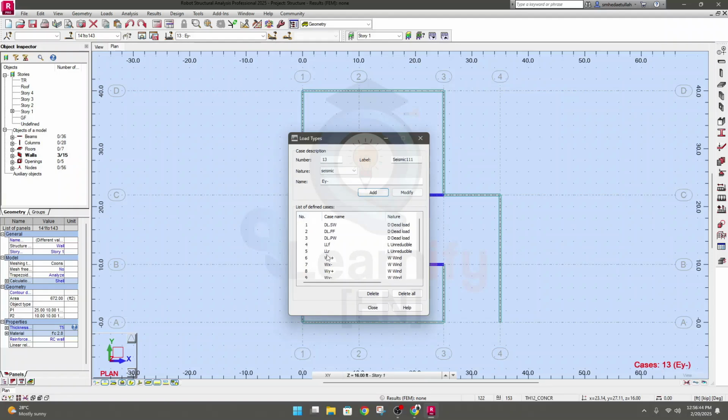And here we have missed something, that was our self weight, and then it is floor finish, partition wall, and it is good to add some water load as a dead load, fluid load. So our overhead water tank load as a fluid load, and if the earth load is available, we can also add it.